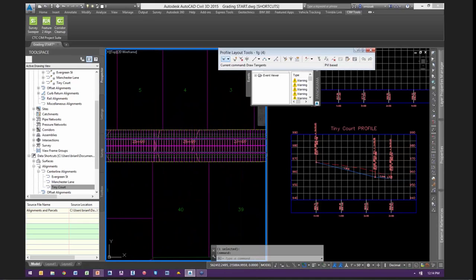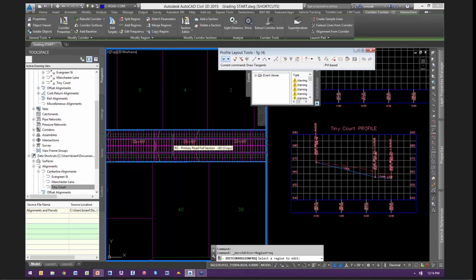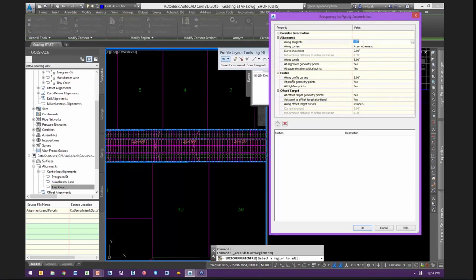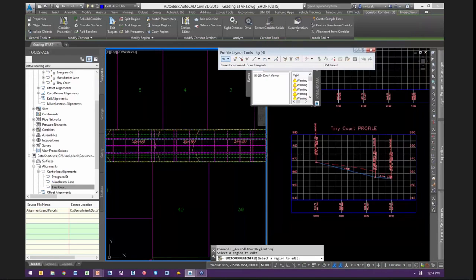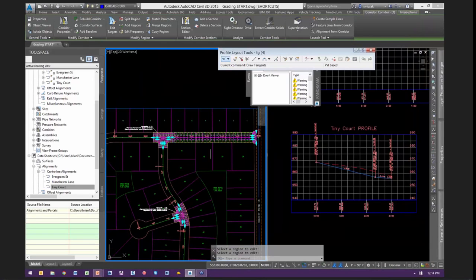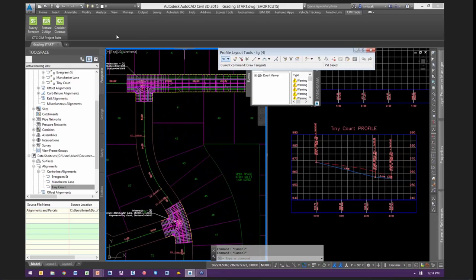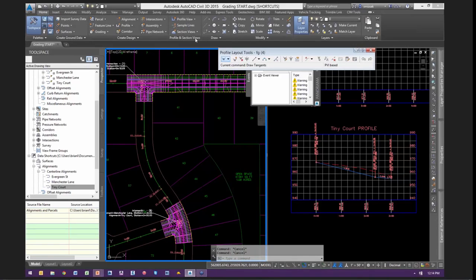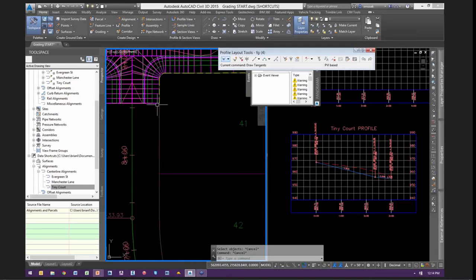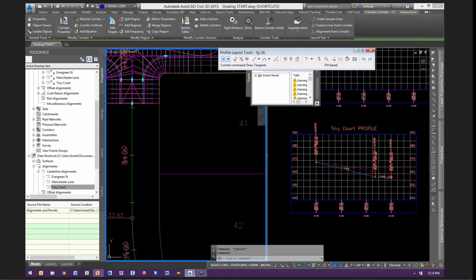So you won't see a visual change, but targets are removed from there and we won't get errors and things like that. So let me go change the frequency of this as well. Let's dial down the frequency a little bit. Okay. So again, we're just modeling to the right of way. And I'll run that copy region command a few more times here. From there